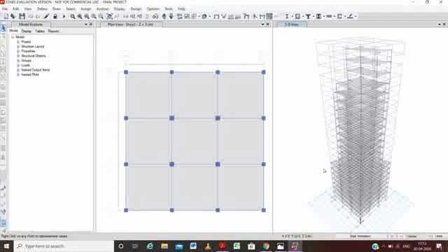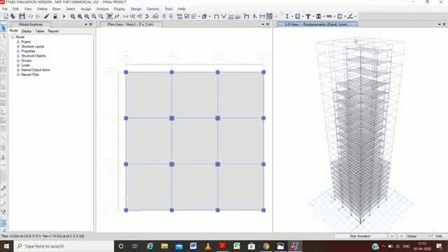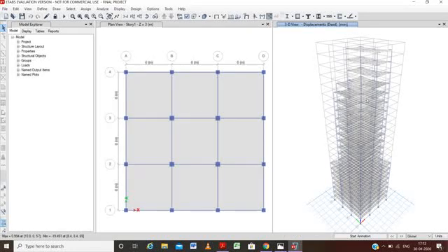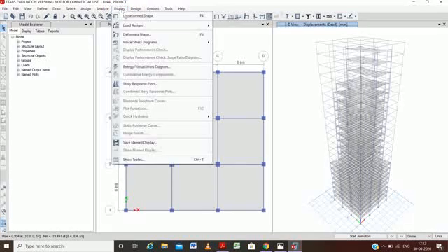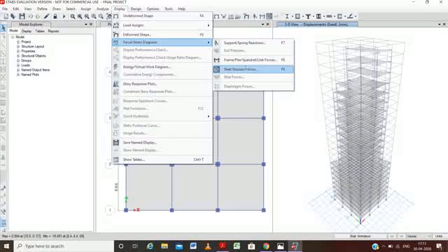And now the analysis has been done, and we can see the deflected shape of each and every structural member here in the 3D tab, as it is the default tab for showing this. If we take the cursor to any member, at any place, we will get the displacement of that place. For more stresses, we can go to Display option, Force and Stress Diagram, and Frame, Piers, Spandrel or Shell Stresses/Forces. From there we can get them.